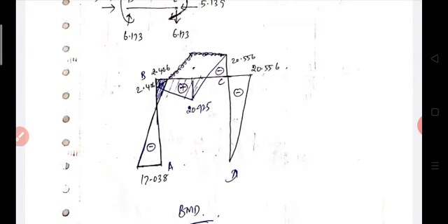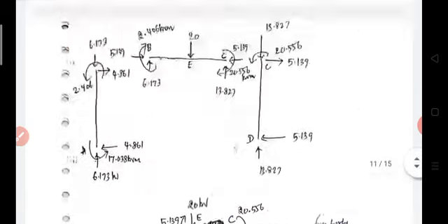The previous one is the superimposed diagram, where we superimpose the fixed end moments with the simply supported moments. First draw the hogging moments, the fixed end moments, at joints A, B, C and D. So what is the moment at these joints? Then draw the bending moment diagram. Then superimpose the sagging moment. Then the final moment diagram will be like this.